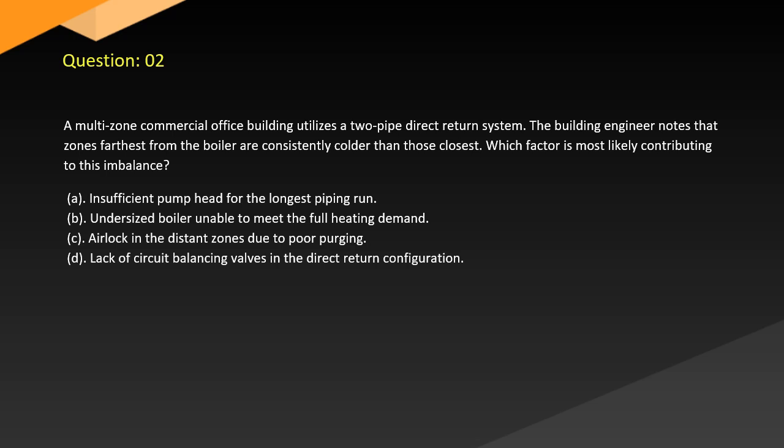A. Insufficient pump head for the longest piping run. B. Undersized boiler unable to meet the full heating demand. C. Airlock in the distant zones due to poor purging. D. Lack of circuit balancing valves in the direct return configuration.